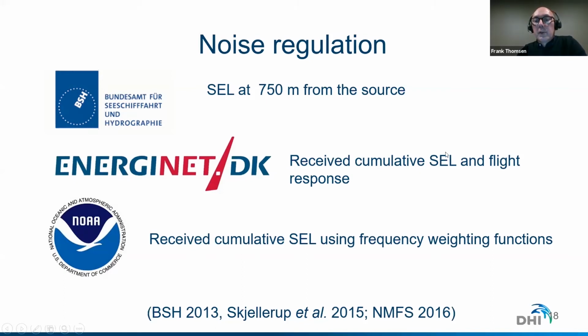Now, this cumulative sound exposure level is important because a pile driving pulse or an air gun pulse is not only one pulse, of course. This comes in series. And this leads to a cumulative dose of exposure at the receiver that can be calculated using this cumulative sound exposure level. Now, NOAA in the US has defined very comprehensive criteria based on received cumulative sound exposure level